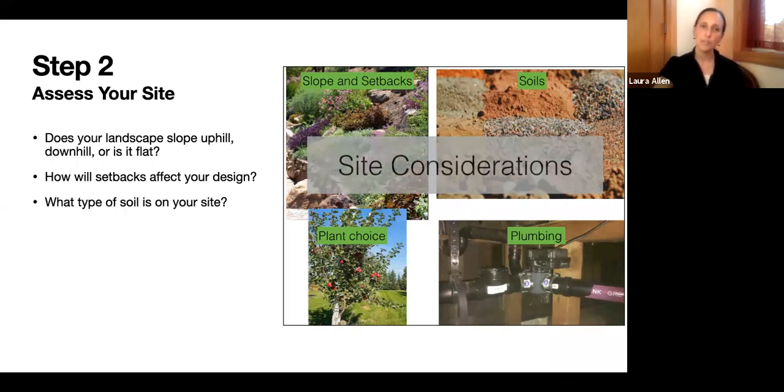Soil type. I mentioned that before. Your soil type will determine how quickly or slowly water soaks down from your site. And it's not going to change how much water your plants need, but what it will change is how big of a basin you need to dig so you don't have puddles or runoff of gray water. Your basin needs to be big enough to soak up all the water that you're sending to it. So it's a sizing calculation that you do. It's quite simple, but you do need to know how much water and you do need to know your soil type.